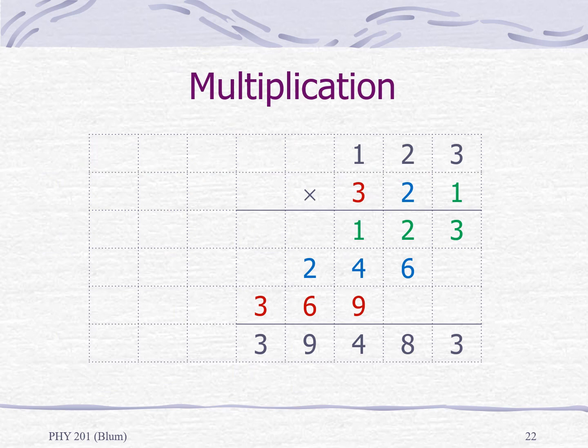Next, we're going to turn our attention over to another use of the shift register, which is in multiplication. So let me remind you of decimal, and then we will look at the binary version. So one way to achieve 123 times 321 is to take the first number 123 and multiply it by the 1 in the ones place of the second number. And so that's that green 123 displayed. Next, we will multiply our first number 123 by the second number's 2, which is in the tens place. And so that's the blue 246. Note that it is shifted over compared to the 123.